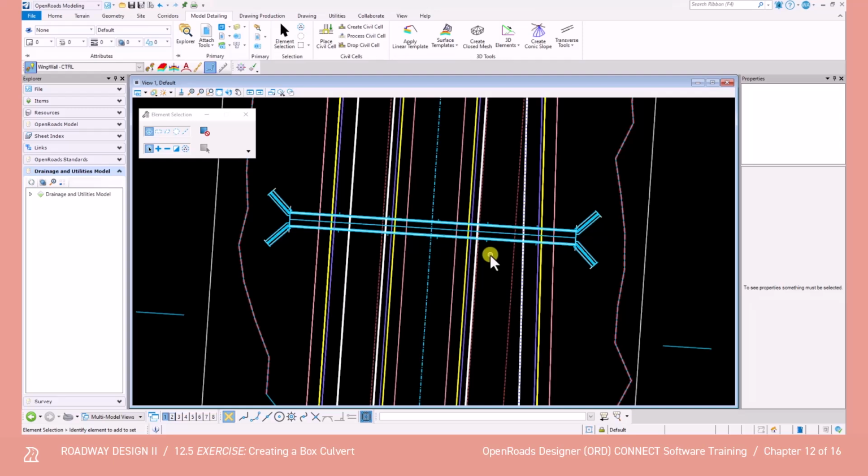Now we need to reference both the Standard Drawing 17-11 and Standard Drawing 17-15 to determine the applicable dimensions for the wing walls. And these will be entered as the parametric constraints in the next few steps. From Standard Drawing 17-11, the big H or fill height needs to be 10 feet, the W or wall length needs to be 18.5 feet, the little h or wall height needs to be 6.5 feet, and then the ST needs to be 9 inches.